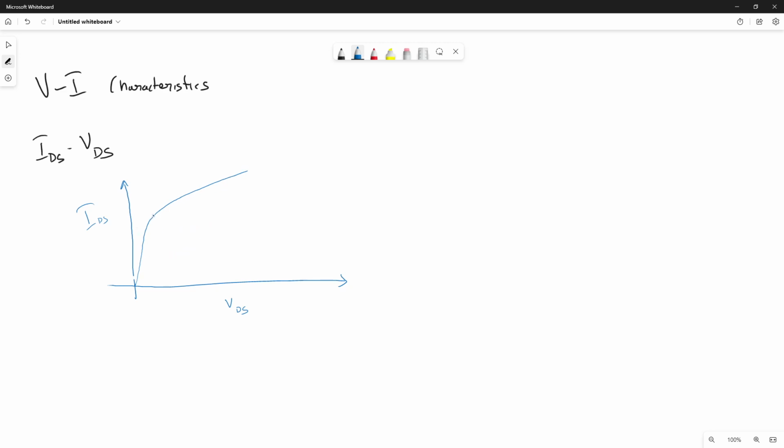Correct. So similarly, let us say at a different VGS, I'm getting a curve like this. And again, it goes like this. Now tell me, this is for some VGS1 and VGS2. What is the relation between VGS1 and VGS2? Simply use the logic that we have previously used. What will increasing VGS do? It will lower the barrier. What will happen when the barrier is lower? The current will increase. That is all. So wherever the current is higher, VGS is higher there. So VGS1 is greater than VGS2. And using this, now we can also define the regimes of operation.